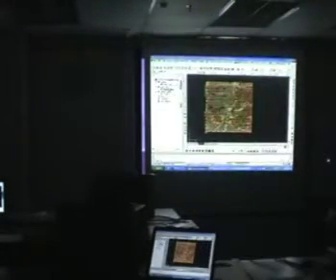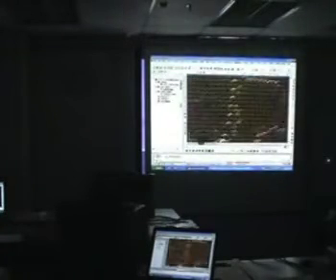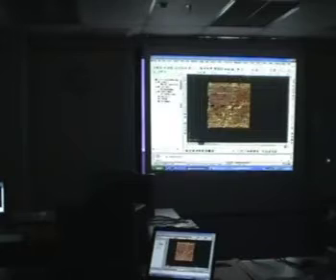Okay, at the moment you find there's nothing added to the drawings because in LandDesktop it's run on a project basis. So although everything has been updated, it's saved in the database, it's only loaded into the drawing on demand. Like let's say now we say, okay, I can't see the triangles, I want to see what the triangles look like.